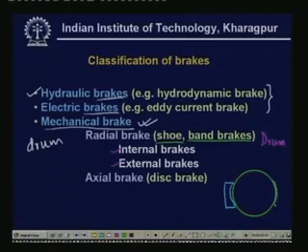We apply two brake shoes and apply force over here. So this is the shoe type of braking, and there is a friction material over here, and this friction material causes the friction force. This is mu times F. So this is how a shoe brake operates. There is another brake, which is the band brake, which could be explained in the following fashion.